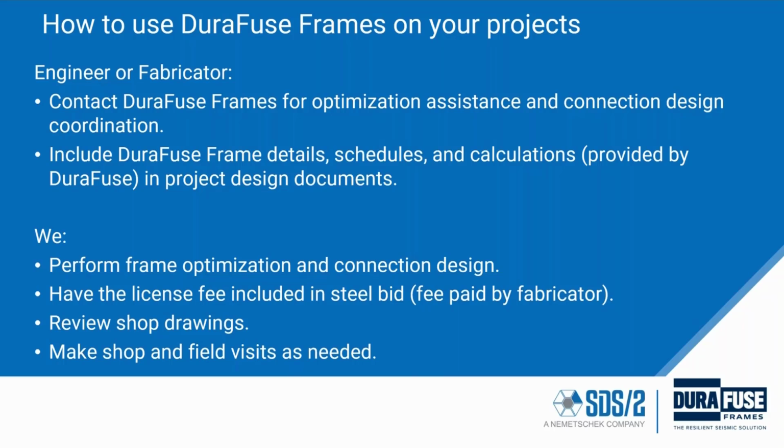We provide optimization of the moment frames and help to coordinate the connection design. And so typically what we do is we work with the engineers and we do the connection design and put together the schedules for the DuraFuse connection and include those on the sheets. And then we also provide the engineers with the calculations and the other things that they need for their design review. We'll perform the frame optimization.